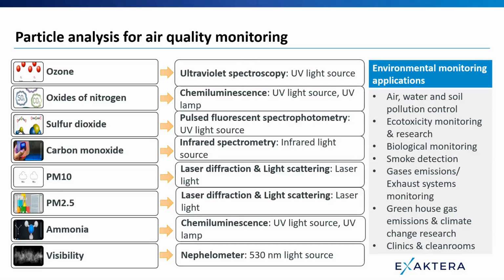Laser-based methods are especially useful in quantifying PM10 and PM2.5 particulates. These are particles with a diameter of less than 10 microns and less than 2.5 microns respectively, and they are of concern because they may cause not only irritation to the lining of the lungs and to mucous membranes and so on, but they can also be absorbed through the lining of the lungs and into the bloodstream, especially in the case of PM2.5 particles, and lead to some very serious long-term health problems.